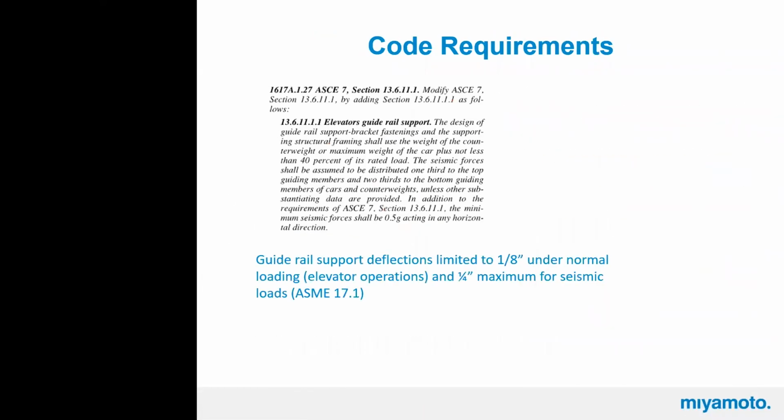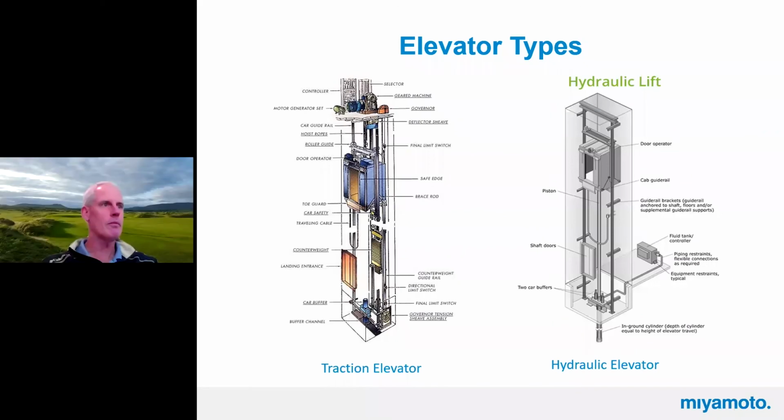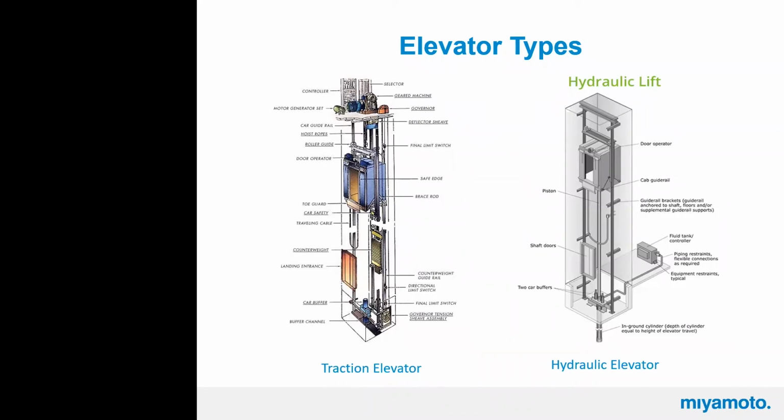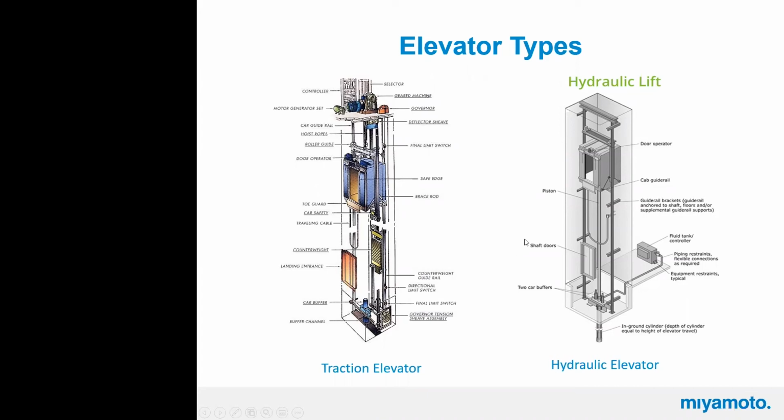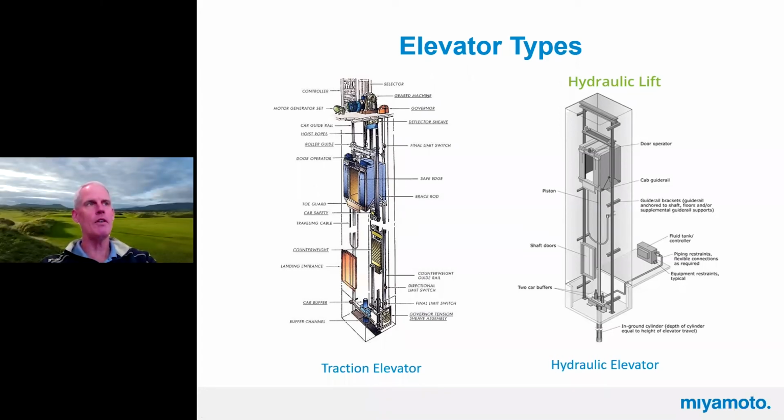Jeff, this is the punch. Hey, we were looking at the traction elevators earlier, right? If you could go back to that slide again, I think it's the second slide or something. Yes, sir. So the machine sits at the top of the elevator, so we do have to design our floors for all that machine load. We do. And that's where Pete was mentioning the deflection criteria. Typically you would have a very thick concrete slab there, has been my experience.